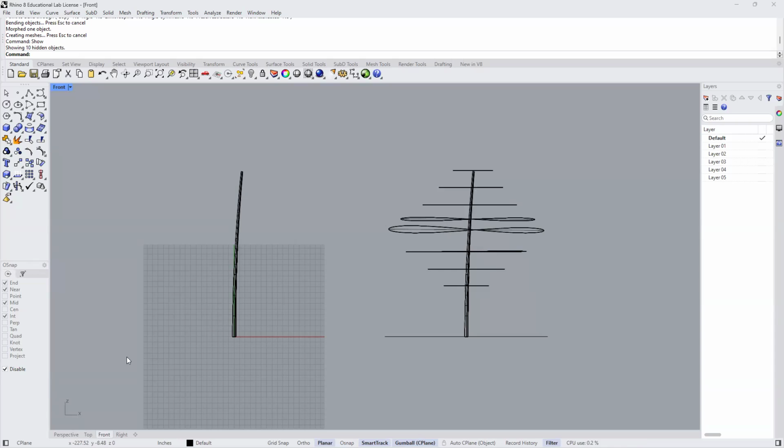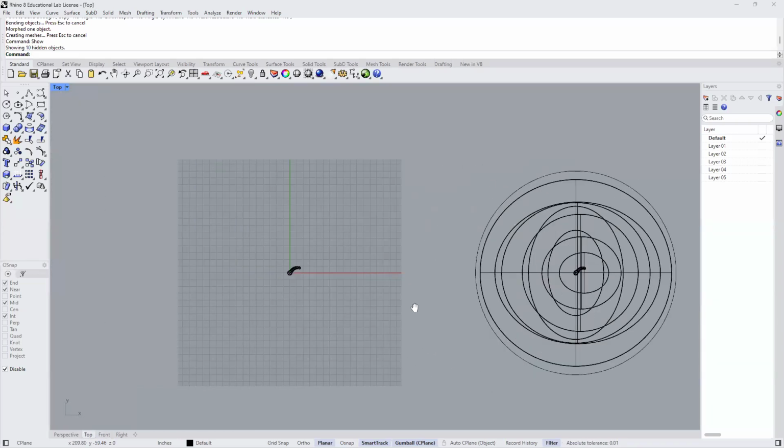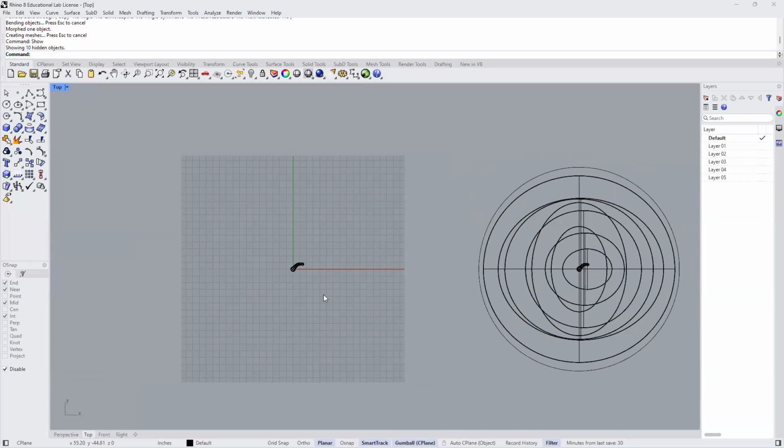I'm going to go to my top view. And then from the top view, let me just zoom out a little bit. And what I'd like to do is draw an ellipse. So I can draw the ellipse by hovering right here on this icon. I can go to the Cascade Ellipse. I have a few options here, but really the one I want is ellipse from center, so I'll pick that one. And then the ellipse center, I'll set it to 0, so I'll type 0, enter.